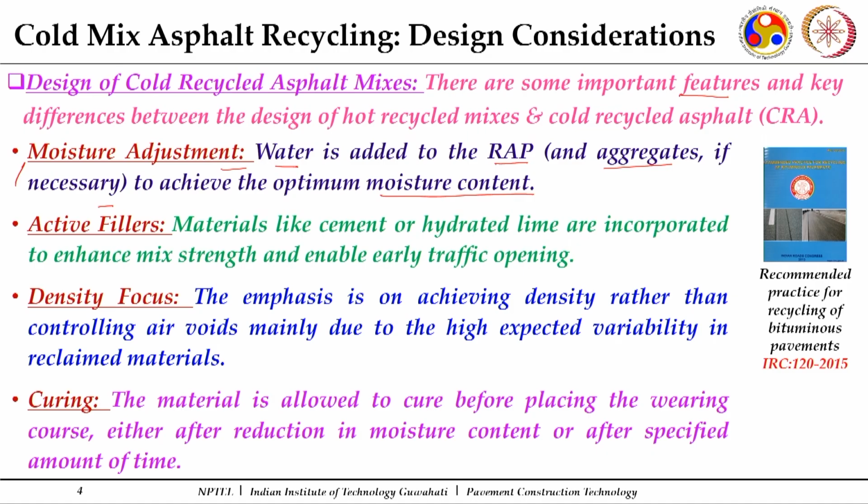So in the case of reclaimed asphalt material, you need to determine your optimum moisture content and maximum dry density to get the required amount of water.